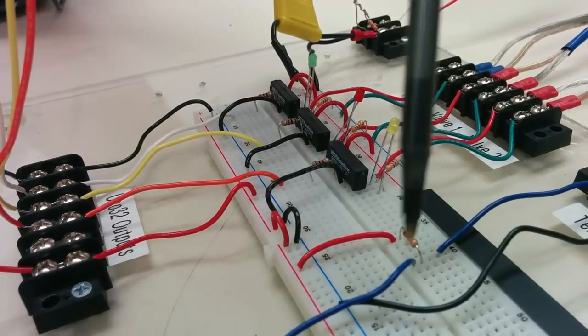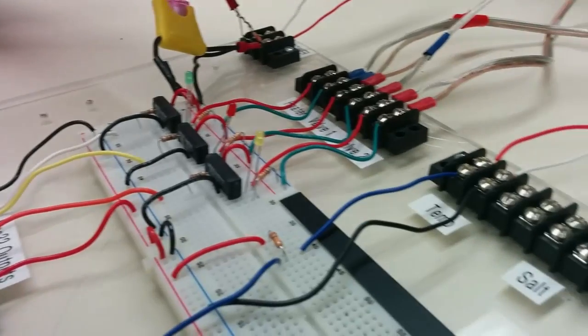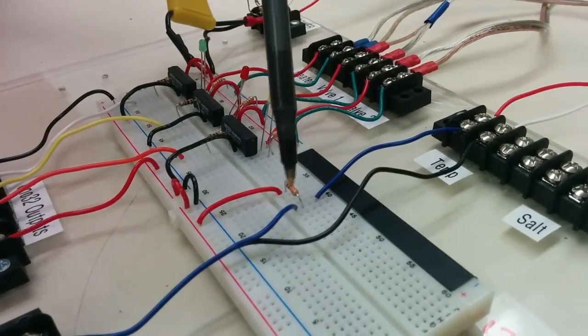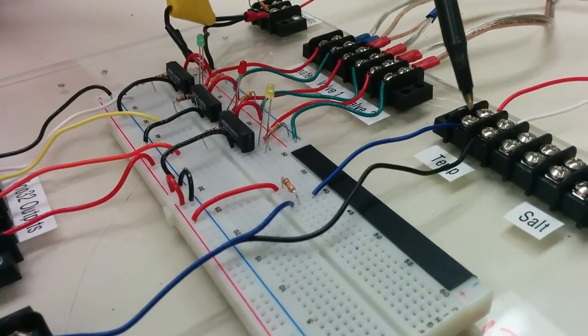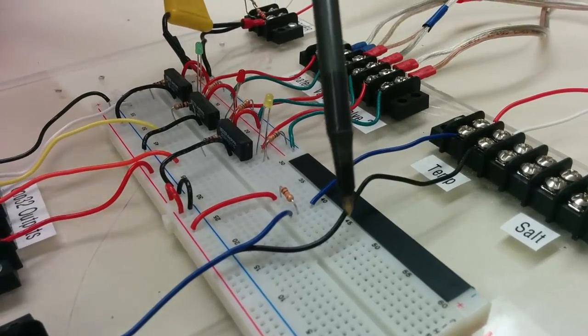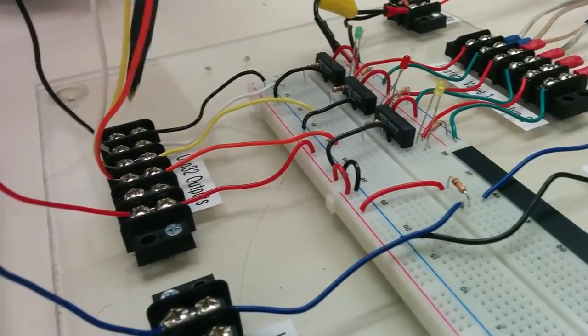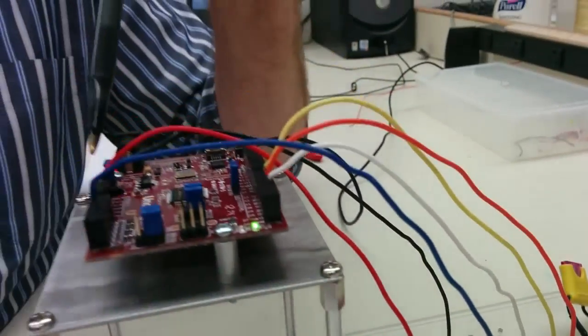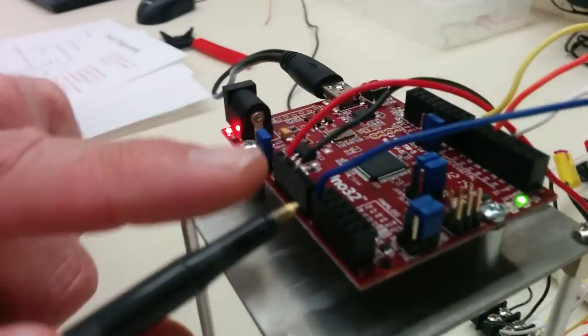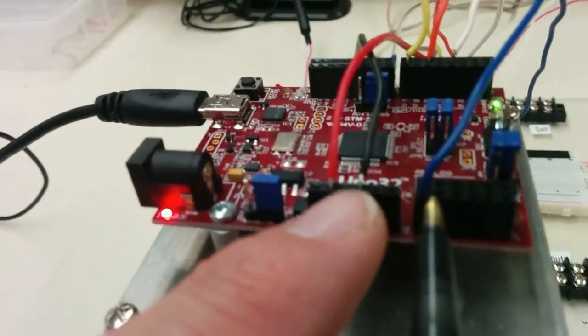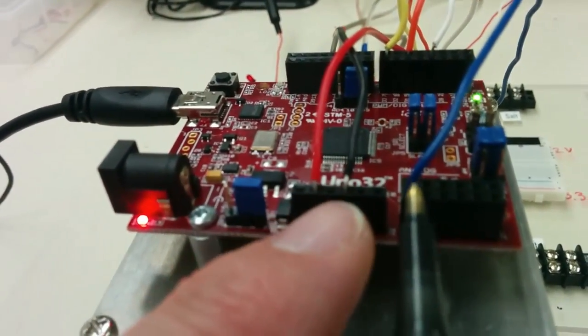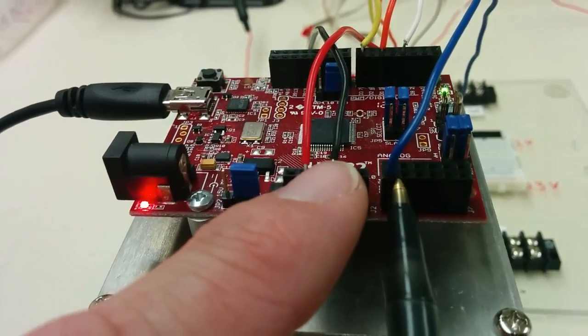And so let's follow the other piece. We knew ground comes out and back here. So we're going to measure the voltage across, essentially across the thermistor. And in order to do that, we come back to the ground, comes back through here, and then back up to the board. So essentially we're measuring that voltage, and what the UNO 32 is seeing is the potential difference between the analog input 0 and ground.